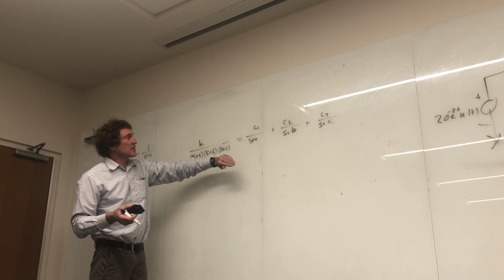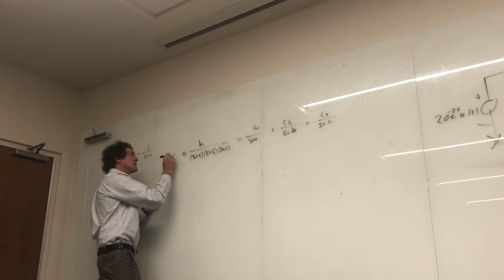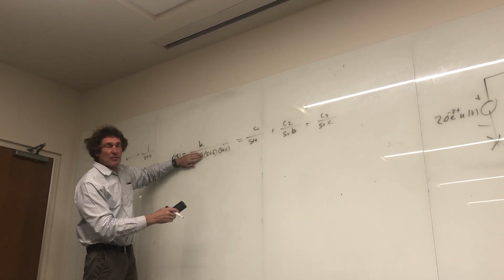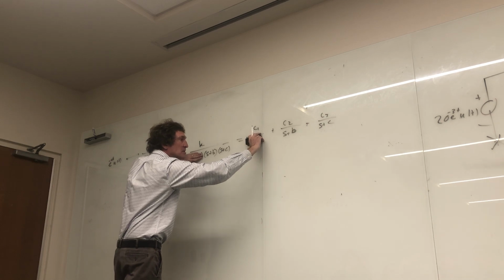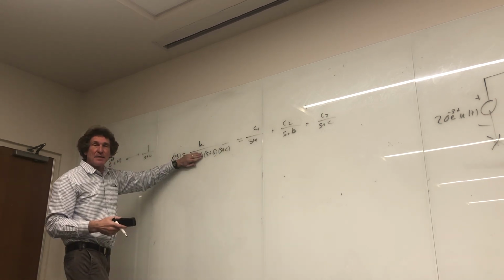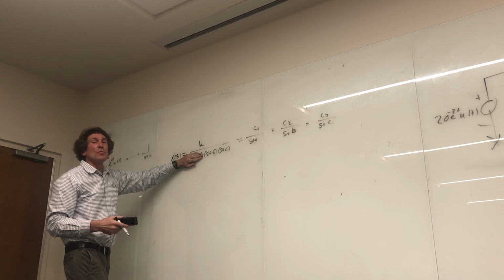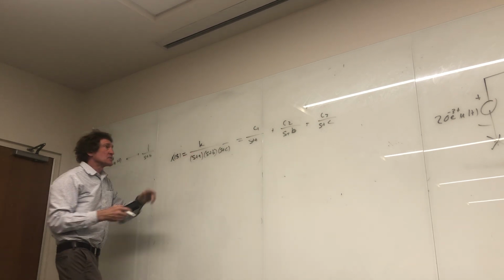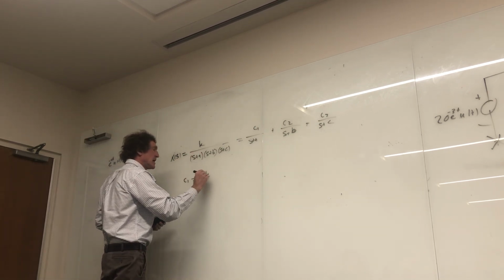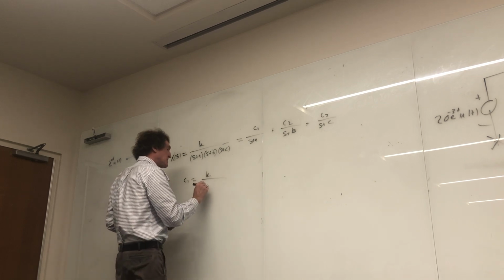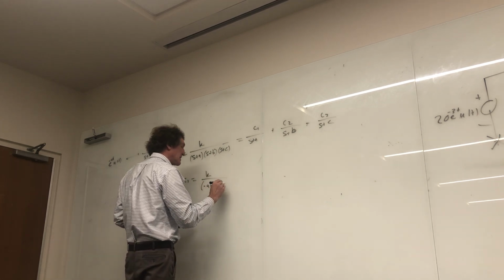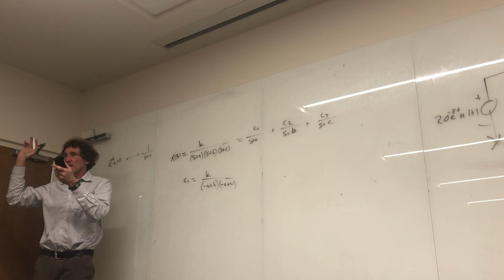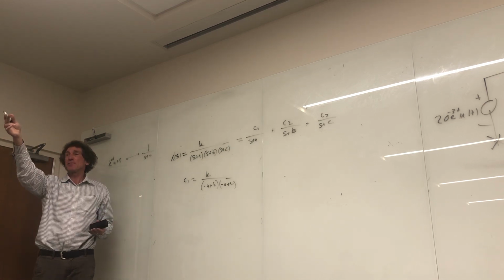So I'm just going to work on this function. Call this my X of s. I'm going to just cover up the s plus a if I want c1. Now I know automatically what I'm really doing is multiplying through by s plus a. And then I evaluate what's left when s goes to minus a, because that's where that pole exists, right? So now I can say that c1 would be equal to k over minus a plus b and minus a plus c. And that would be c1. How many see this right here? You see it? I'm asking you, do you see it? Because I want to make sure everybody sees this.